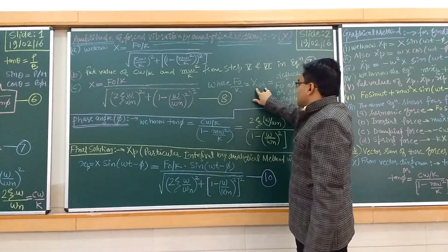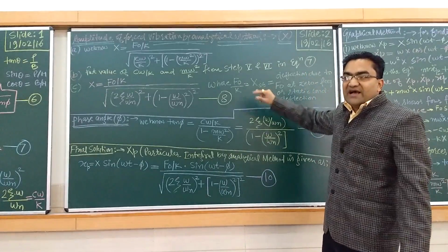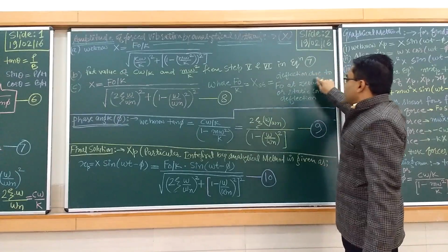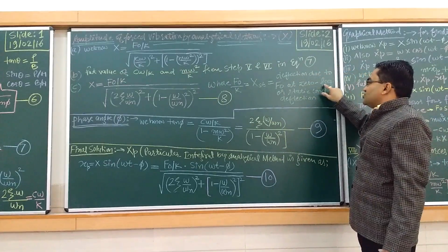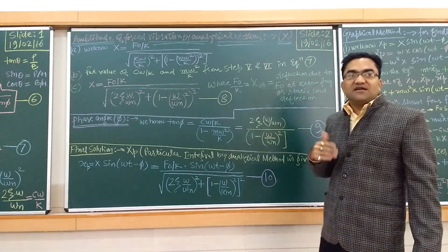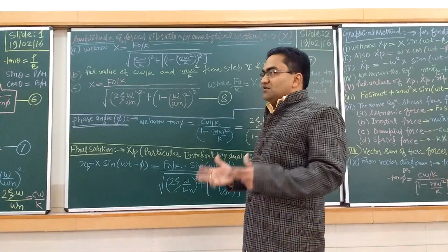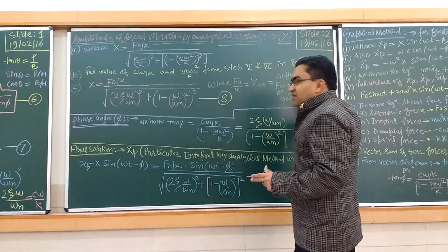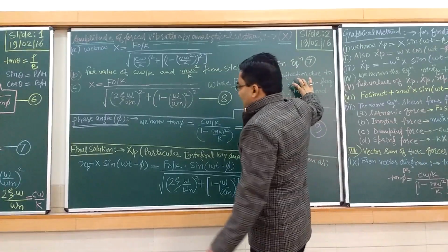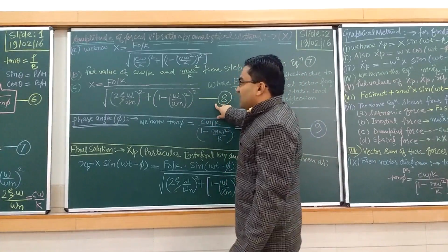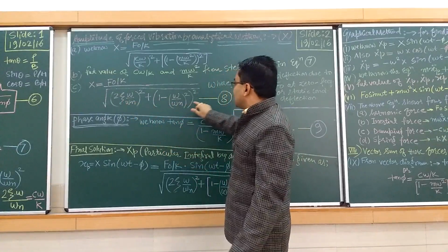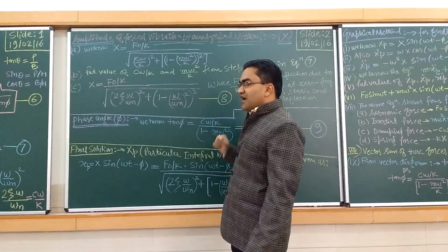This is known as your X first, the deflection due to f naught at zero frequency, or the static condition, meaning the system has not yet started. So this is the deflection at the very first sight. This equation, in the form of zeta, omega and omega n, I name equation number 8.